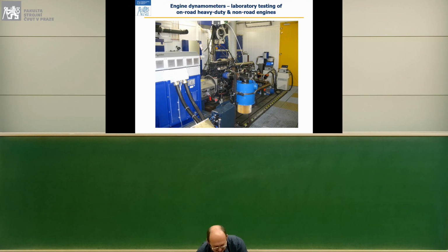We have the engine. This is an Iveco 6.5 liter 6-cylinder turbocharged engine, fairly favorite for city buses, about 180 kilowatts, coupled by a shaft with a dynamometer.